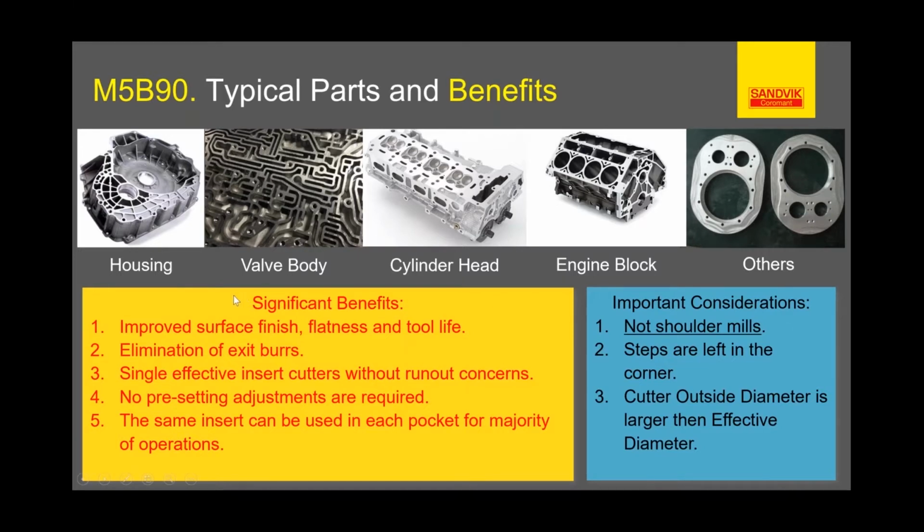So the benefits of this tool: good surface finish, good flatness, extremely good tool life, elimination of the burrs, and no run out problems, because you don't have to worry about one insert to the next, because each one is set to a different height. No presetting required. They're all fixed pocket. And we can even put the same insert in every pocket if we want. And I'll talk about that a little bit later.